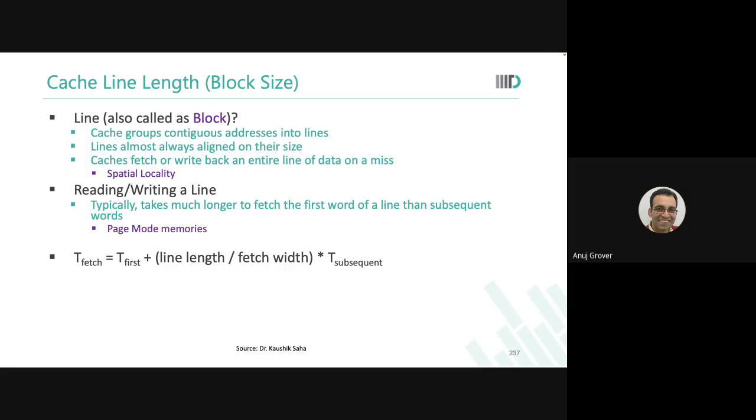In the DRAM, internally in the DRAM. But they don't come directly because your bus width cannot be 256 words wide. From your DRAM chip to your processor chip, you only have a 1 byte, 8 bits wide bus. So words will, only 8 bits or 32 bits, whatever is the width of the bus, only that many bits can come in one go.